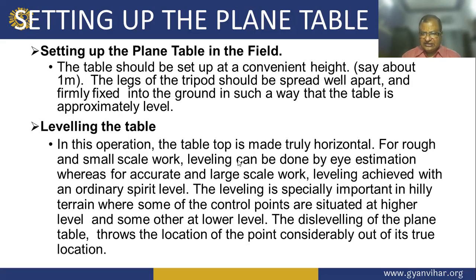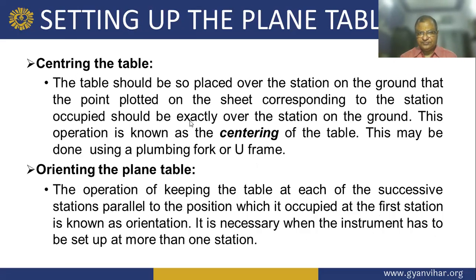The leveling is especially important in hilly terrain, where some of the control points are situated at a higher level and some at a lower level. The disleveling of the plane table displaces the location of a point considerably from its true location.